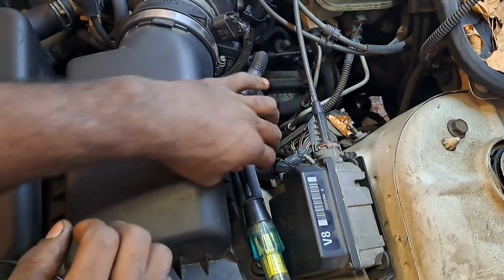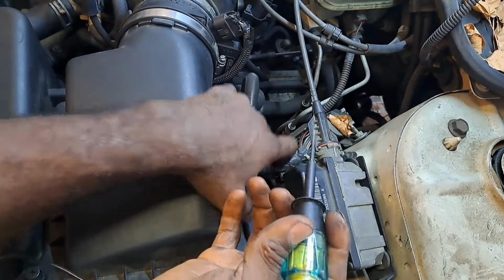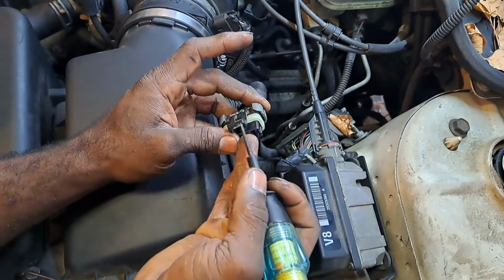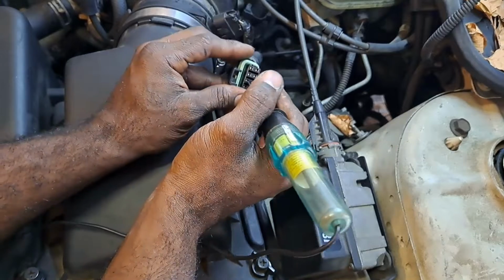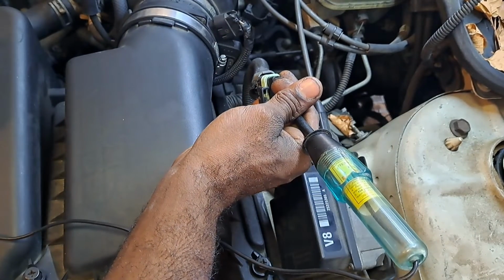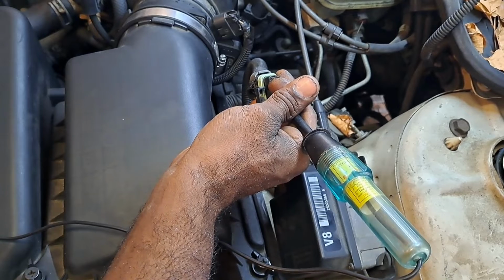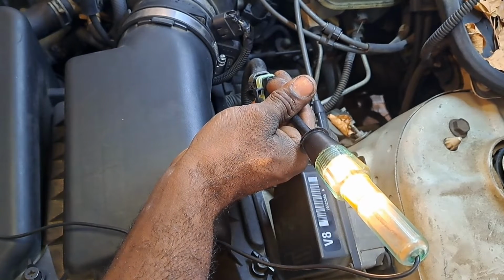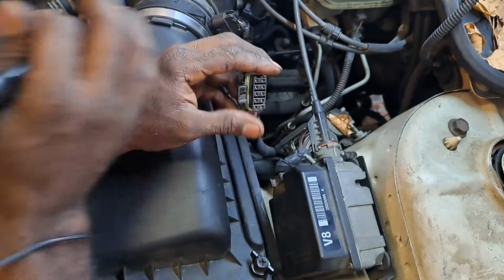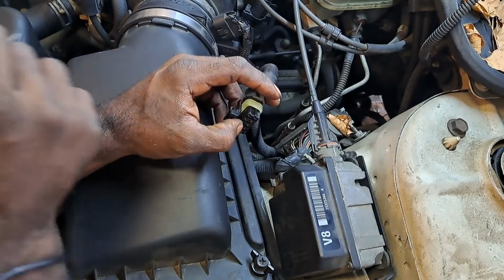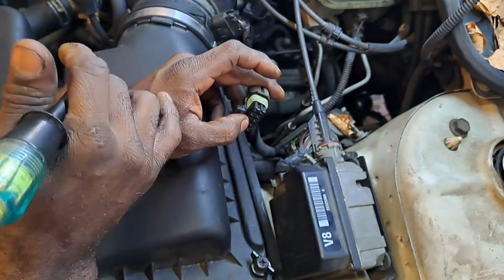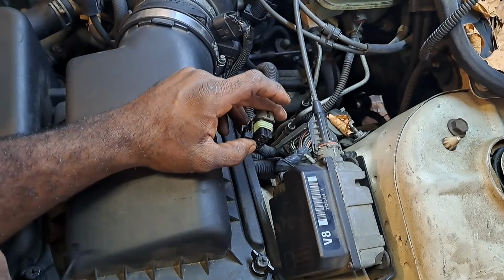So we should have an allowance, or we should be enabled to activate the cruise control. I'm on ground, there's nothing. If it was to illuminate, that would indicate that I have positive voltage. So if I go to positive, which causes it to illuminate, that indicates that this is a ground signal. So to enable this cruise control to operate, I need to supply a ground signal.